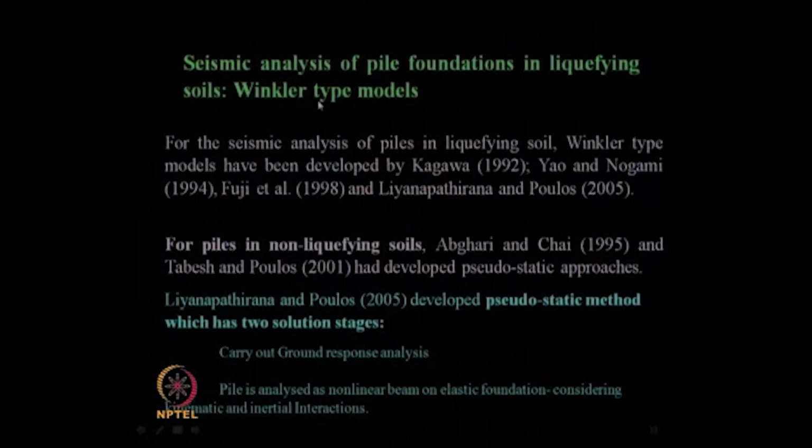So, that concept of Winkler spring model is extended for the pile foundation also in liquefiable soil by various researchers. Winkler type models have been developed by Kagawa in 1992, Yao and Nogami in 1994, Fuji et al. in 1998, Liyanapathirana and Poulos in 2005. So, for piles in non-liquefiable soil, when you do not have any liquefiable layer, but still it is under earthquake or seismic condition, you still have the additional horizontal load which needs to be considered.